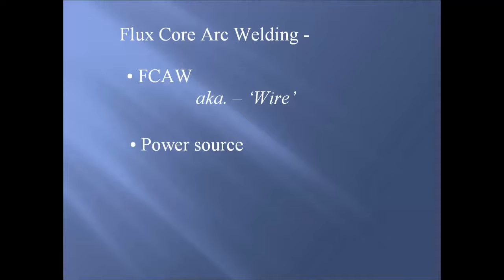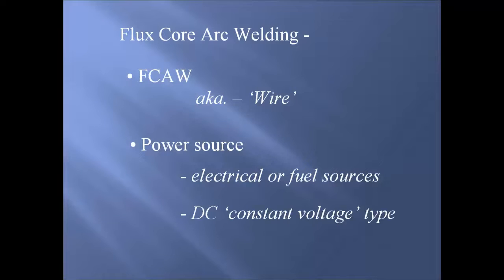There are two power sources, and they are the same as with SMAW, either electrical or fuel sources. And the recommended current is direct current, constant voltage, typical.